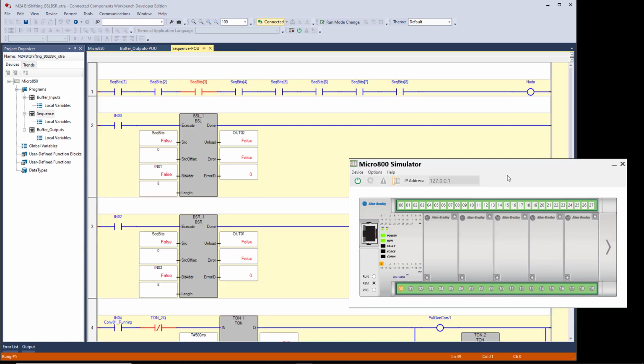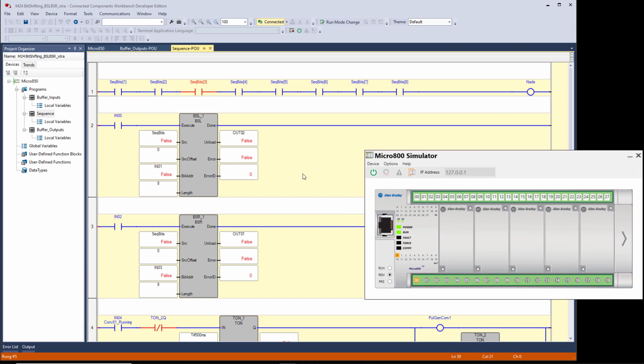at on a conveyor. Well, we have a few things left to tidy up yet in this lab project. We did the bit shift left. We spent all of our time so far working with the bit shift left. The only difference between the bit shift right and the bit shift left is the direction that the bits get shifted, which means the bit address is going to be different and the unload is going to be different. So if you have a length of 8, you see these are both 8, the bit address is input 1, the bit address is input 3. The difference is where that is inserted.